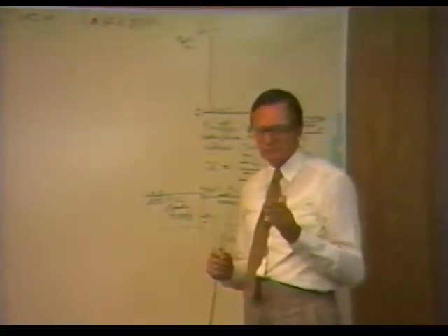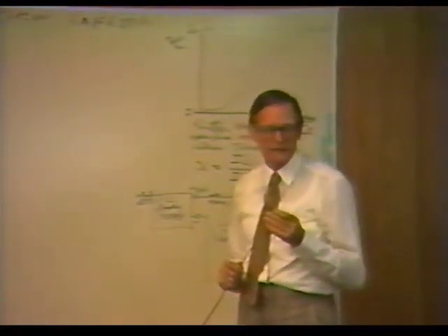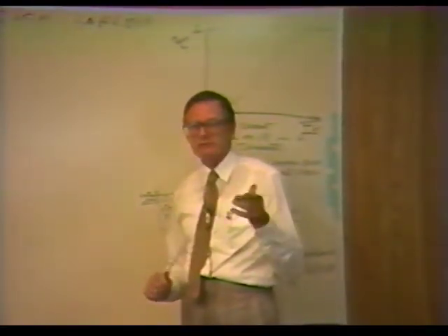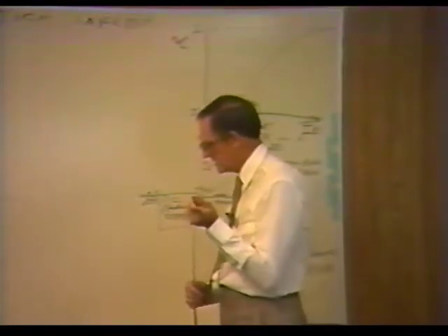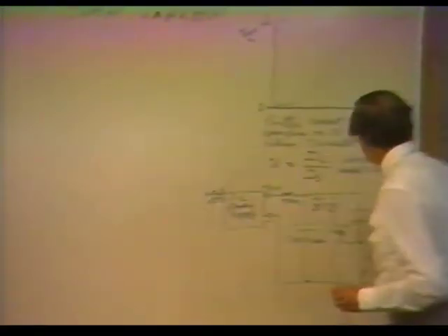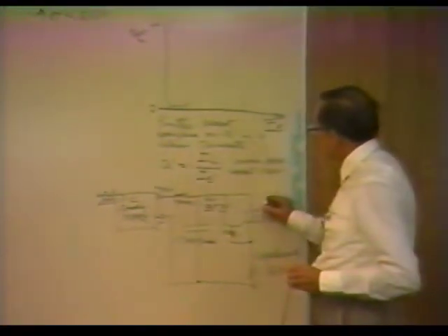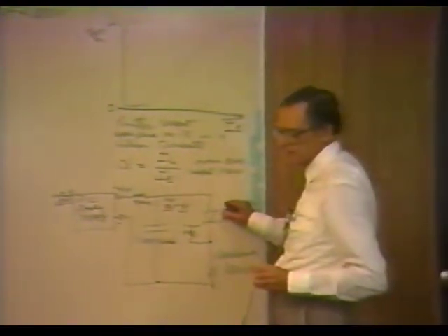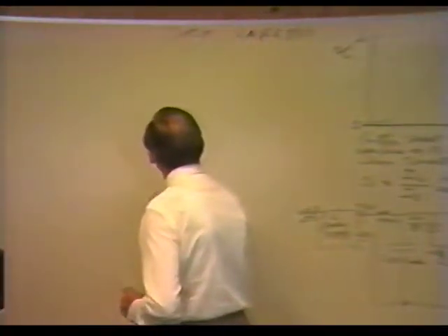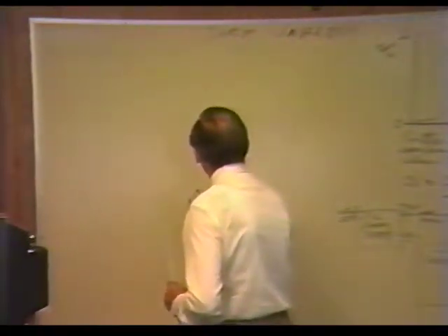It was a tube. We used them here at Sandia. I was probably the last fellow that ever had anything to do with a tube around here, except the special tubes that we use today, like the Krytrons. But the hydrogen thyratron was a very effective tube for the same purpose that an SCR is used for, an off-on switch. And here's the way it worked. First of all, we had something we called the cathode.